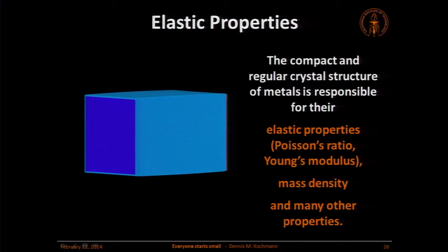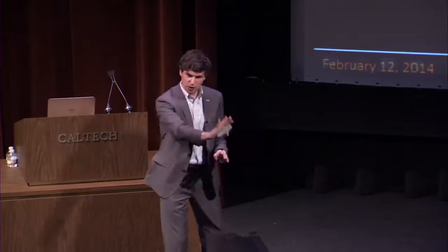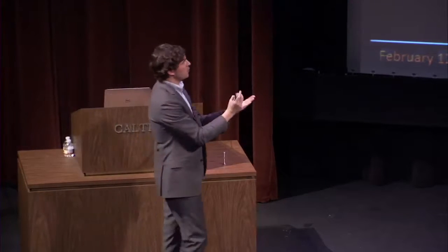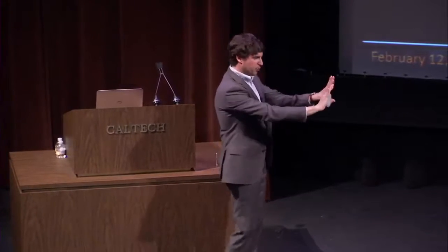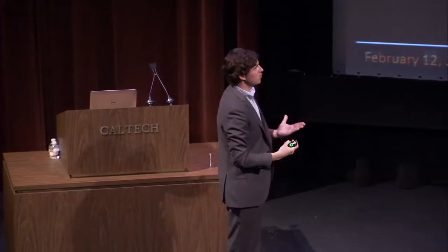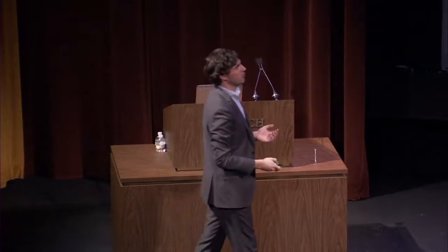The same for the stiffness, Young's modulus. When you push on the material, of course you need a force to deform it. You want to press the atoms closer to each other. And this depends on the interaction. You have to press hard so that atoms that want to be further away get closer. This is what gives rise to the elastic properties. It is the crystal structure. Once you know how they are lined up on the crystal lattice scale, you know exactly what these properties are.